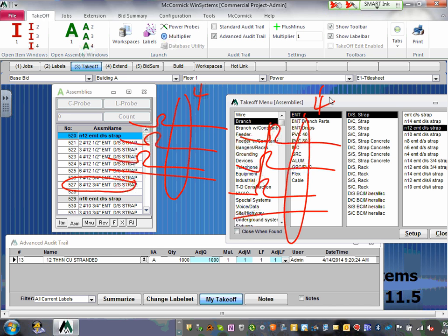If you need a 7th circuit, pick another 3/4 of an inch and run it with it, okay? Or 1/2 an inch. So everybody understand? When you're taking it from the ceiling all the way to the panel, from a junction box to the panel, you can group up to, based on this, 6 circuits. 8 conductors, 6 circuits. What happened to the ground, Karen? The ground, we're pulling the ground through EMT conduit.